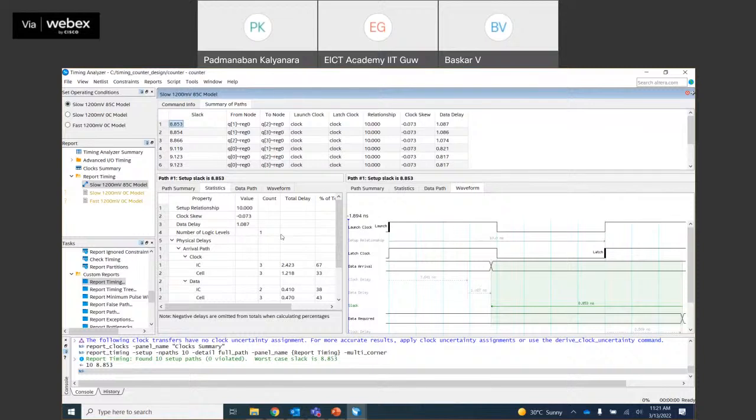For example, if the number of logic levels is 5, it has to cross 5 logic levels to reach the second flip-flop. Before it crosses 5 logic levels, there are chances that the clock can reach the second flip-flop. Therefore, it would be a slow logic path. We have to be very careful. That comes from our poor coding style. If you write Verilog, VHDL or SystemVerilog code where you have more logic levels between two flip-flops, there are wide chances that the design may not meet timing. You will have a setup violation. You have to be very, very careful.